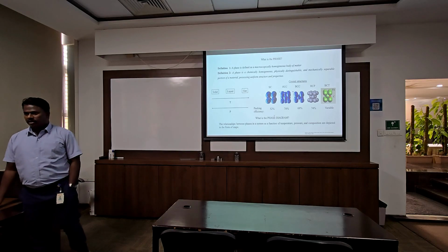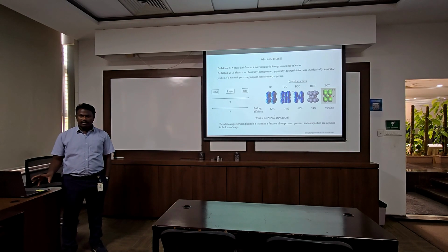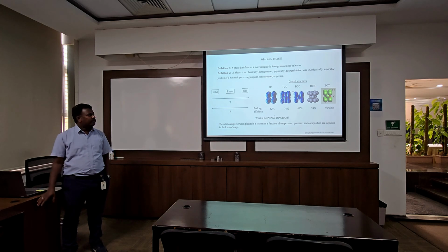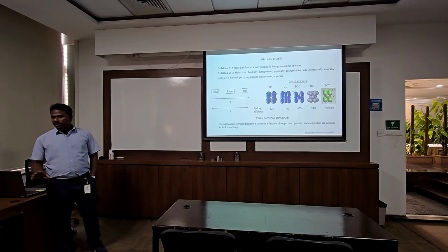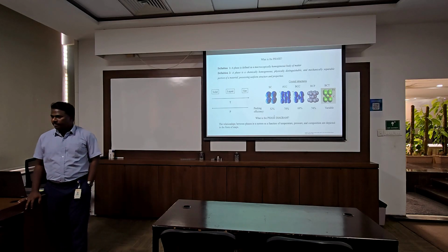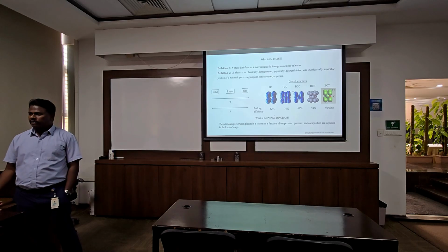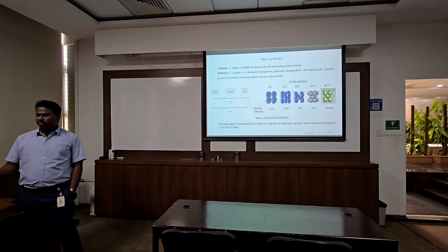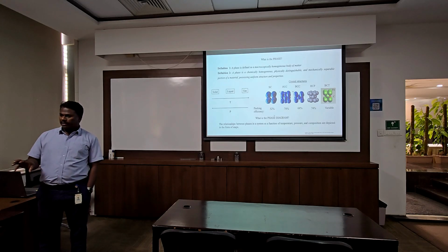Yes, that is true. So basically at room temperature, more densely packed crystal structures are more stable. That means FCC or HCP can be stable. As you increase temperature, it can go to BCC and then any further phase, whatever it is. Depending on the phase, if you increase the temperature, the FCC will transform into some other phase. Generally, what I'm conveying here is that at room or low temperature, those densely packed structures are more